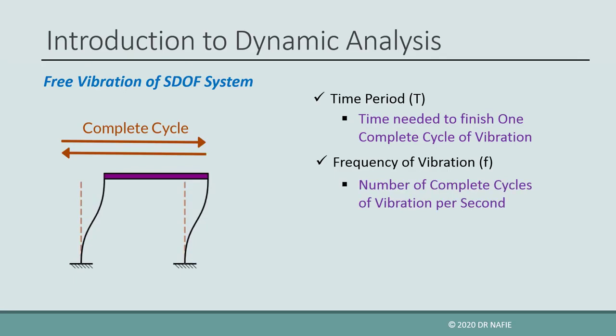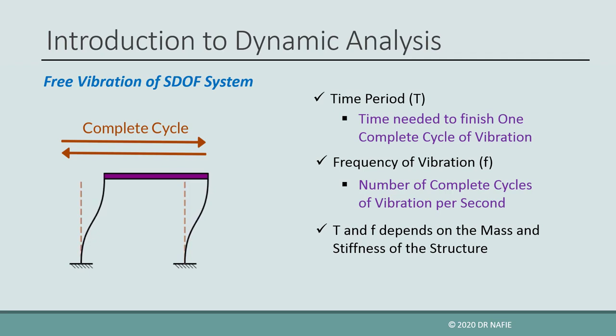One important feature of this free vibration is that the natural period and the natural frequency are always constant for the frame, and don't depend on the magnitude of the force that initiated the vibration. They only depend on the mass and stiffness of the frame.